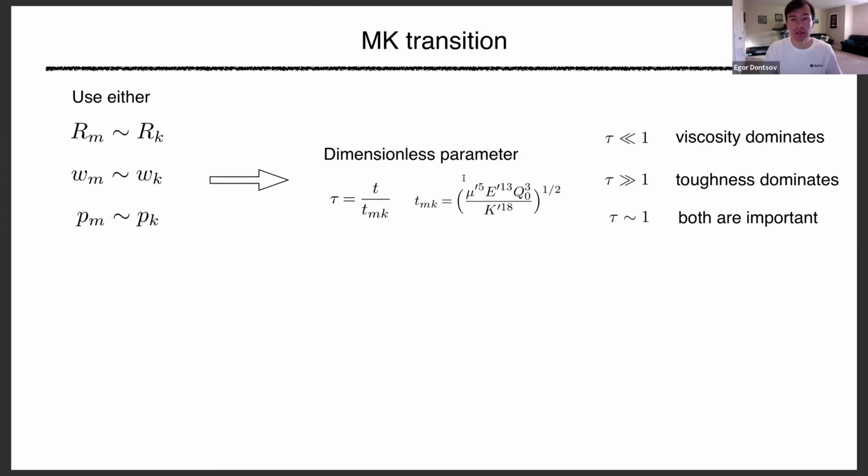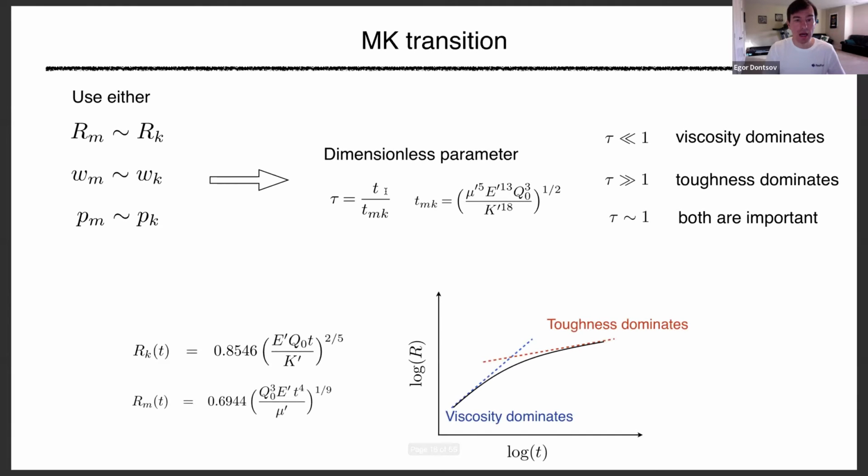Again, you can look at things like, what if you put zero toughness, how large tau is going to be, and the same for large toughness, what if you put very large toughness? But these are dimensionless parameters. It's not just large toughness. You can have a change in modulus or injection rate or viscosity, or toughness or injection time, and they all affect the result. And here's again a very important conceptual understanding.